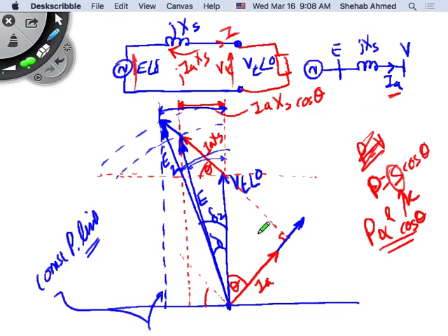Take two cables next to each other. I want to supply a load, and this load doesn't care how much current it consumes, but I want to put these two cables next to each other to supply it. What's my limit? My limit is how close I can put these conductors next to each other without insulation. Or if I'm going to insulate them, then I have to make sure that the insulation will withstand the voltage, right? That's one condition.